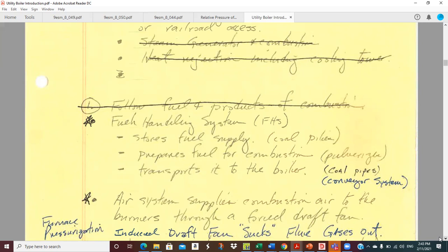So if it's frozen, they have this huge heating shed. It's like either 2 or 4 megawatts of heating elements, and it's just an open shed. There are doors, but they stay open on the ends because the rail cars are going through. They slowly pull a rail car through there, and it's probably as long as 4 rail cars, and they blast the side of that rail car, top, bottom, all over, with heat from electric resistance heating elements, enough to melt enough of the water so when they open the door, the coal will fall out.